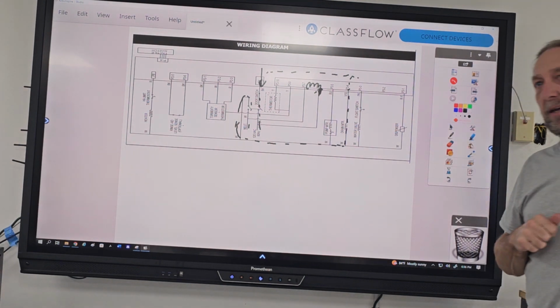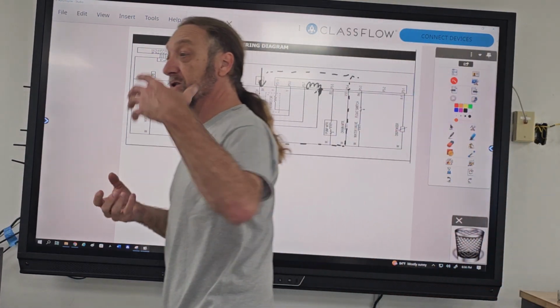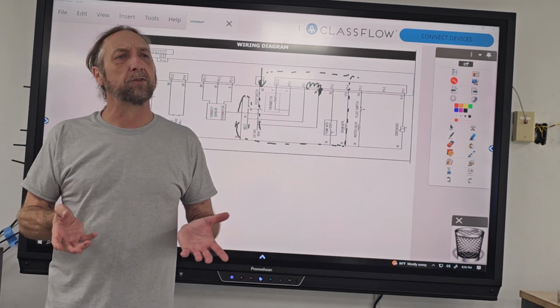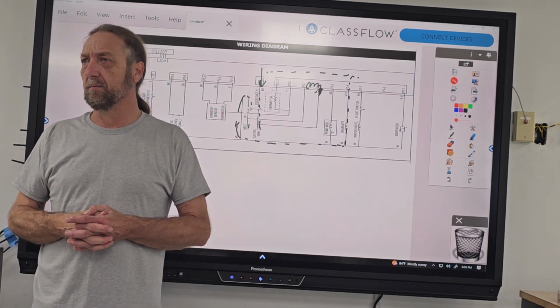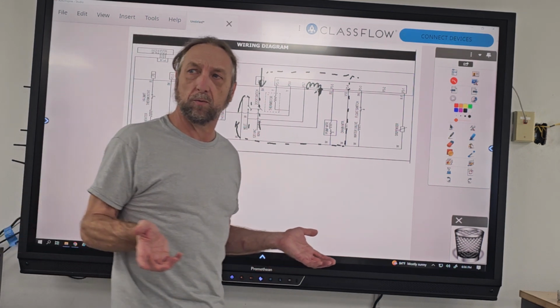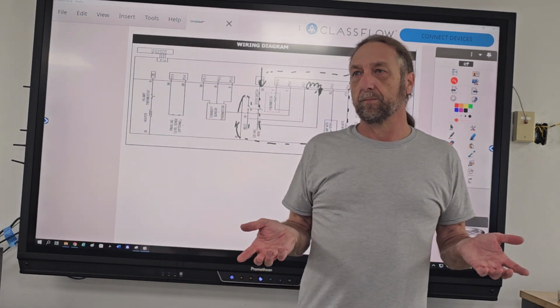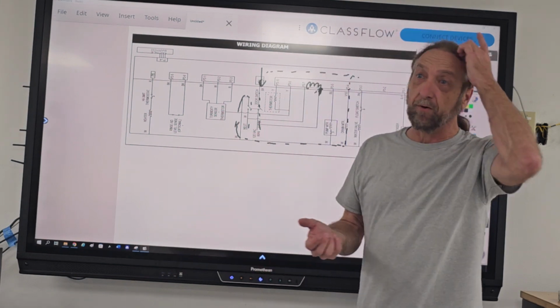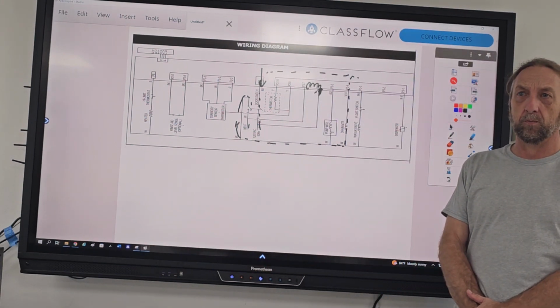And what I'm trying to say is, we still have to determine whether it's my board or my door switches. Do we always have to do a voltage test? No. What test could we do? We can do a resistance test. Resistance or ohms test? And what type of ohms test would you do for a board?